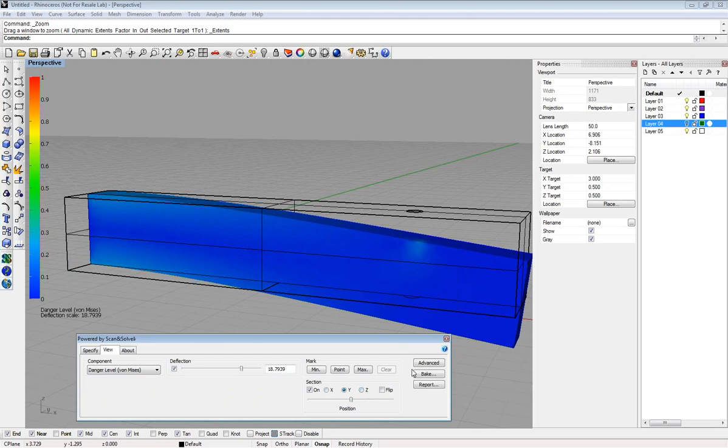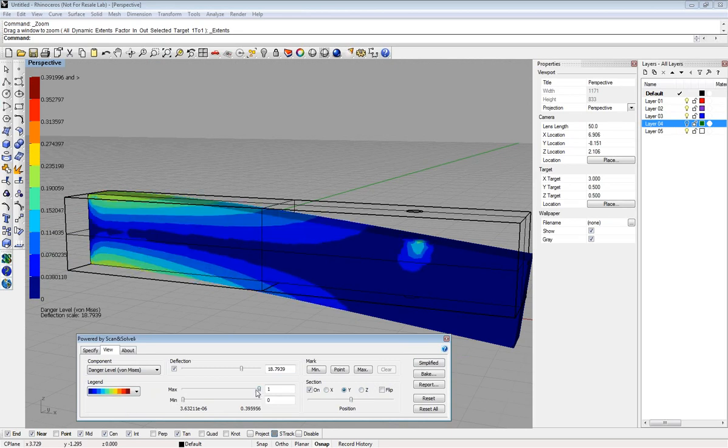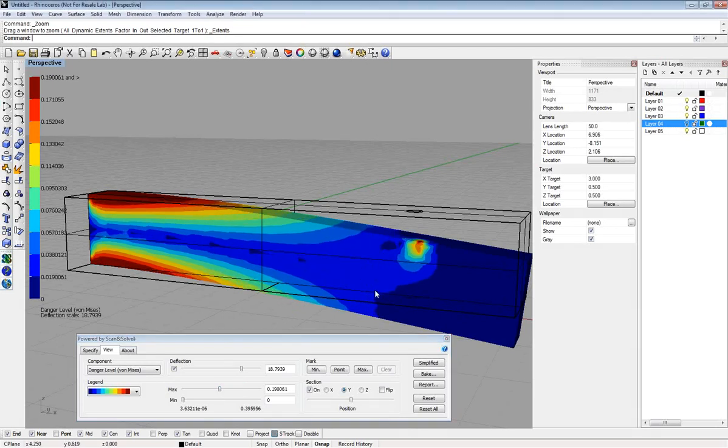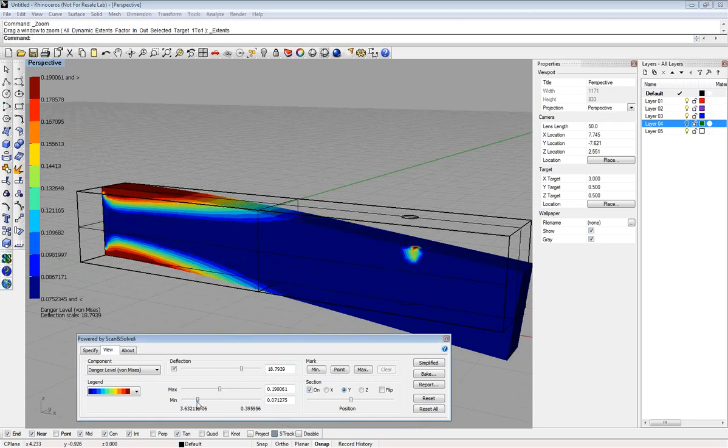Now, inside this View tab, we also have the Advanced button. The Advanced button switches over to a different type, allows more controls for the view. When we do this, we can change the legend scale, the color scale that's used for the legend. So I can switch to a stepped color scheme. I can also change the maximum and the minimum of the legend, so that you can gain some extra information about it. So you can zone in on or hone in on particular ranges of values.